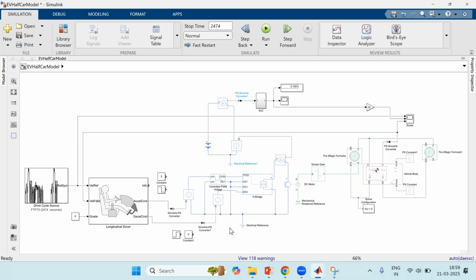So to address that, we'll keep disc brakes for all the wheels, as the current IC engine vehicles have. The similar brake will be provided. Then that means the electric brake is not sufficient? It won't help for the instant stop. It takes some time, because the moment of inertia will be available on the object, right?